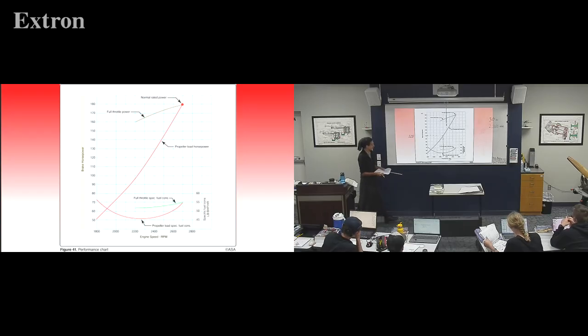And then we come back here, 2,300, and go up to this to find out how much fuel is being consumed. Come across, and we come right about here. So 0.45 to guesstimate, split the difference.